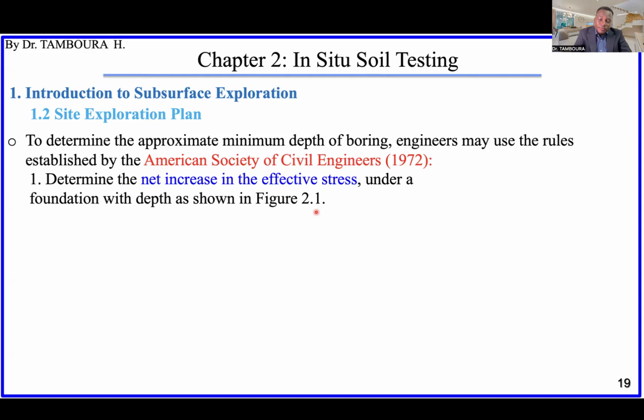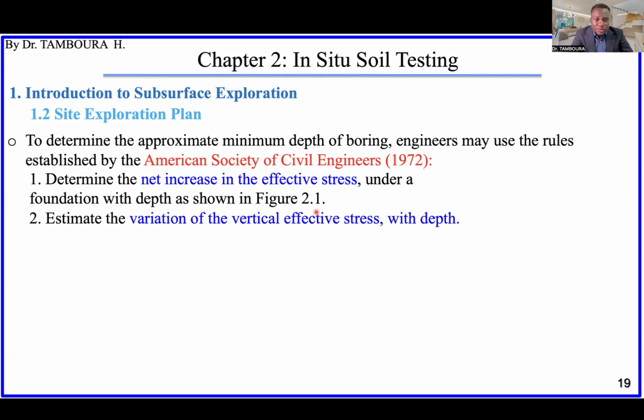I mean, the effect of the loading on the ground will decrease when you go deeper. This figure will explain it very soon. And we have to estimate the variation of effective stress with depth. That one is easy, right? The unit weight multiplied by the depth.